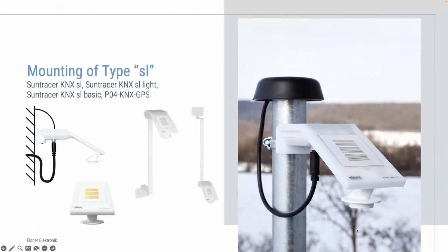Another point is that the electronic wind measurement is more expensive than the mechanical wind measurement. This is a big difference because the electronic wind measurement needs to be calibrated in a wind chamber. This you do not need to do with the mechanical wind measurement. Also, the components for the electronic wind measurement are more expensive than for the mechanical wind measurement.